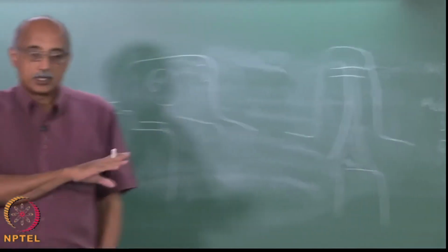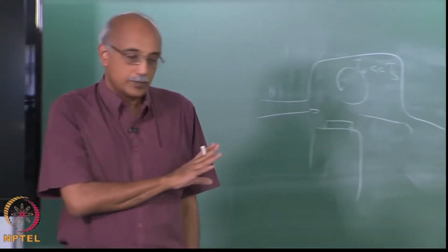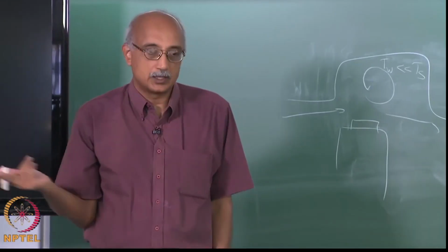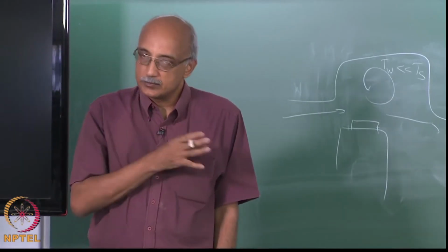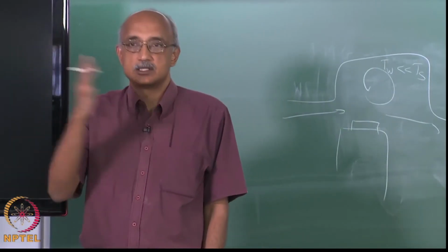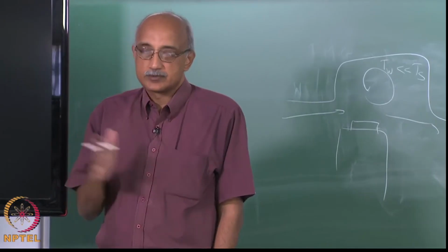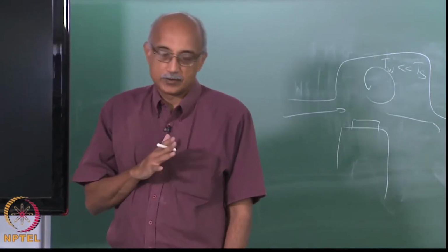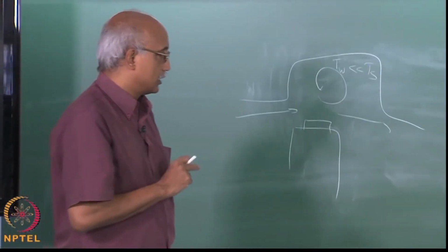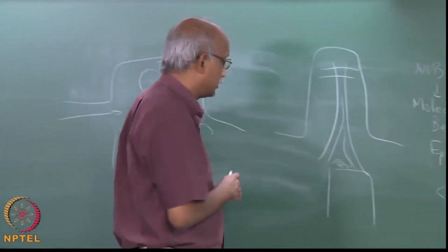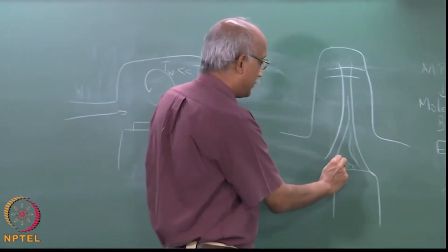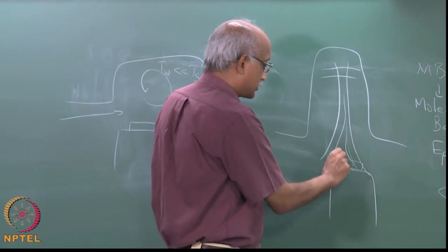If you are going to use a horizontal flow reactor, many of the things that we have talked about earlier in terms of the flow dynamics, controlling the velocity profile, so that you enter with a uniform or plug flow, which then turns into a parabolic flow, become very, very important to achieve in the case of an MOCVD reactor. In the case of the stagnation point flow reactor, the primary thing that you would want to look at is what is happening in the vicinity of the substrate.